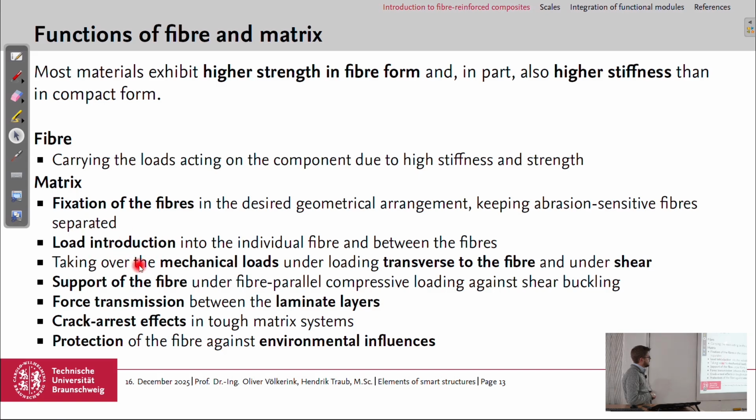They serve as a load introduction into the fiber. So you have to bring the loads into the structure, which is done also by the matrix. And they're taking over the mechanical loads when you have loads transverse to the fiber, so not in fiber direction but perpendicular to it. Then the matrix also carries load, as well as under shear. And under compression, they prevent the fibers from buckling, from having a stability failure of the fibers.